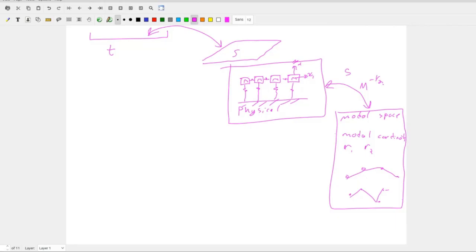So today what we want to do is start in our physical space, right? We want to go down to our modal space. We want to select some of the modes that are important to rebuilding our solution. We're going to solve for those modes and those participation factors, which we've referenced before but not really talked about. And then we want to come back to the physical space, and by coming back to the physical space, we can replot our time series displacement.